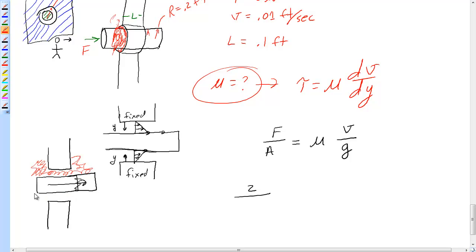And that one region is right here. In this region is where that profile exists. Out here, that profile doesn't necessarily exist, and there's nothing to produce a resistant force back in here anyway. The fluid's just being pulled into there. So the area is the wetted area that exists all along in here. It would be 2 pi the radius, times the length.